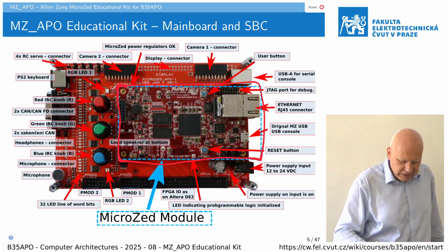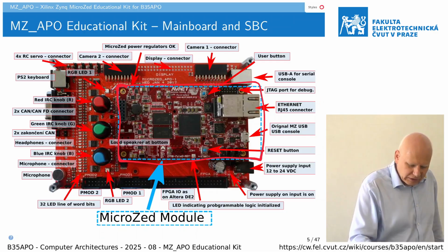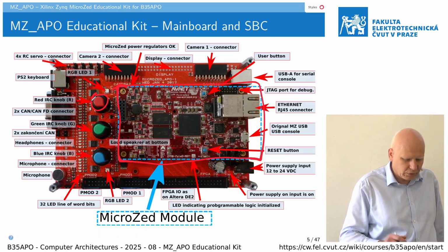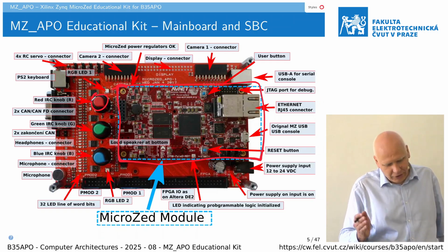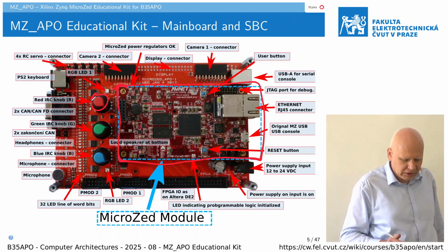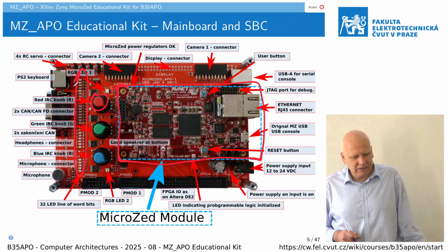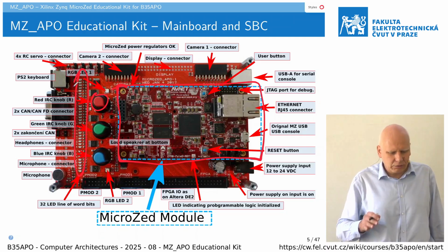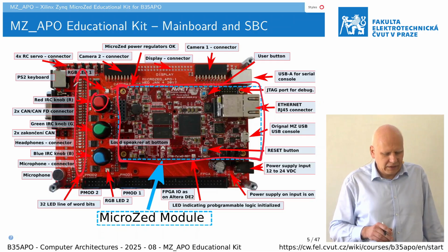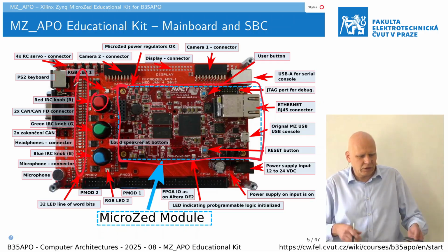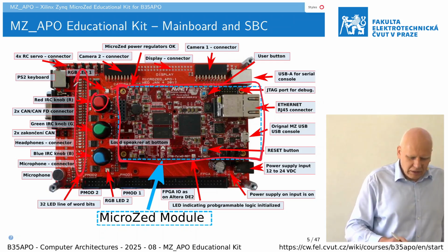Then we have some peripherals, those knobs which allow you to tune the input value, 24-bit, for example a color or position on the screen. Then we have a set of LEDs which are directly mapped into the address space, so you can change the individual LEDs. Basically, if you write a 32-bit word into some address, then you can light some LEDs on and off.